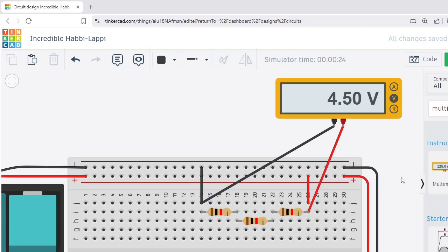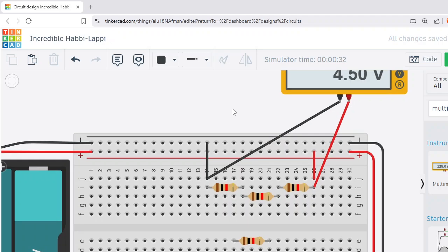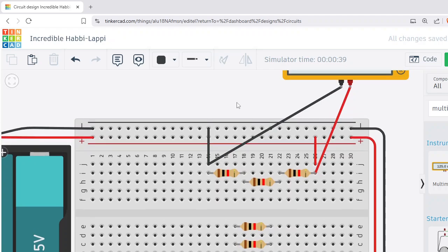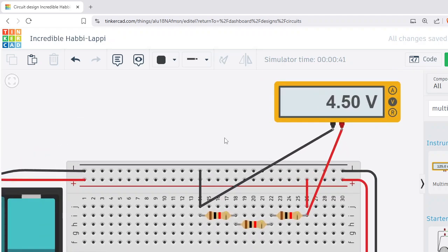Are we okay so far? Class 10 students, you would be understanding this much more. Okay, good. What do we do now? Now let me tell you how to check current. When we check voltages, the voltages are checked with the multimeter in parallel with the system.